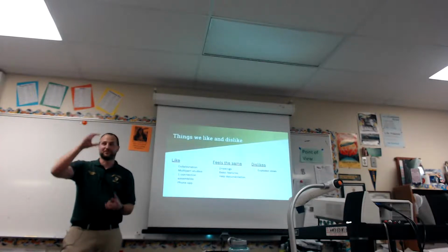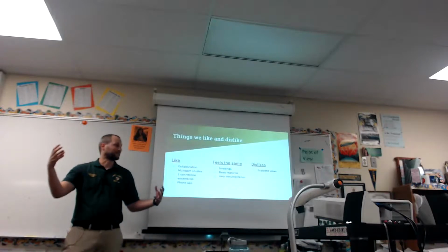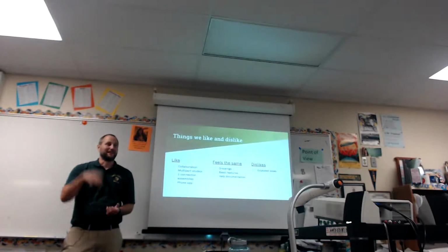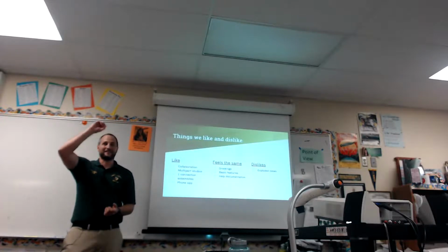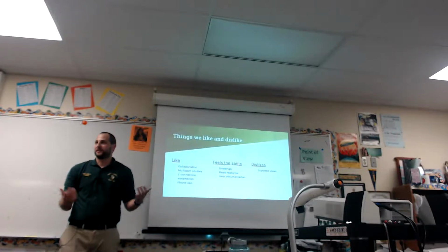It's not simple exploded clicks and buttons. You actually have to go through, make a new assembly basically, and offset all your connections with some values to explode it out. This is something that Onshape has basically said, yep, it's fine. They have a posted document that says, here's 3 methods you can use to get around it. Exploded views aren't something we're supporting at this point. So that's a downside, something that we don't like.